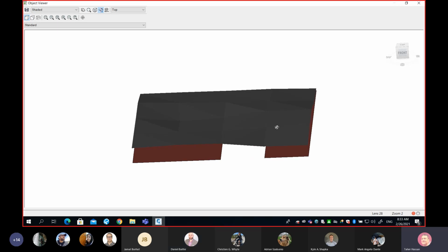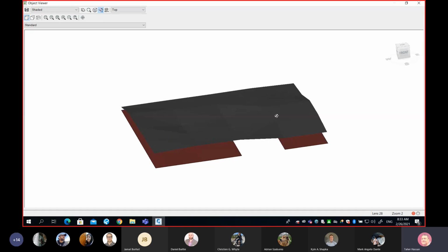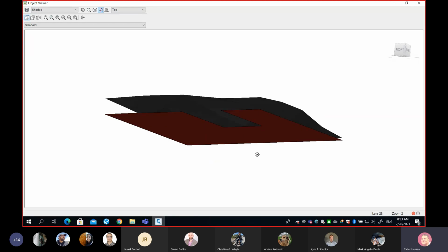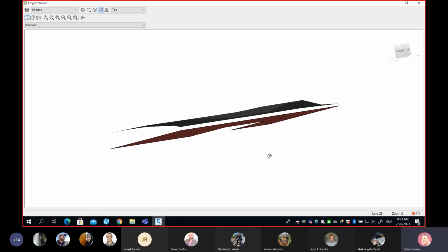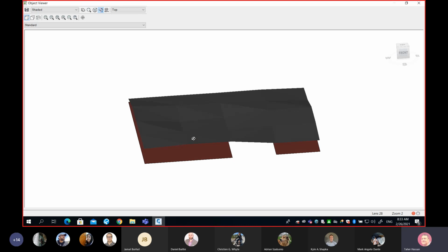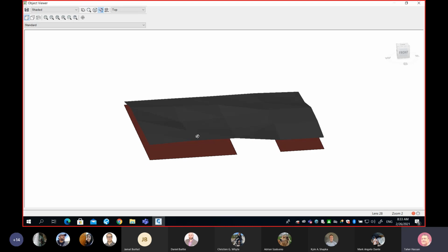Okay. Any other opinions? Any other thoughts about this one? Please think. It's a tricky question, by the way, not easy. So I'm asking you, do you think I must remove the building from existing ground, or I can do the calculation right now? Because we don't have anything underneath that area now, would that mean that AutoCAD might not calculate that square anyway, because it doesn't have anything to reference? Yes, sir. That is the perfect answer.